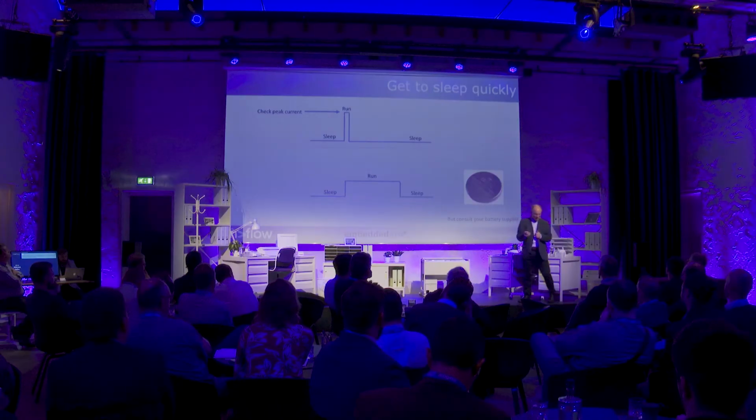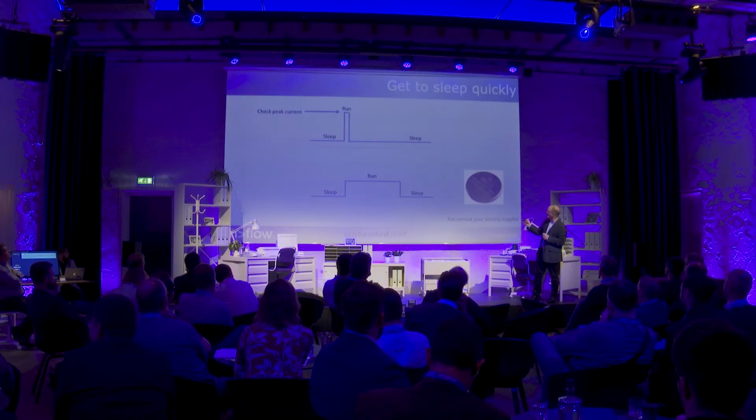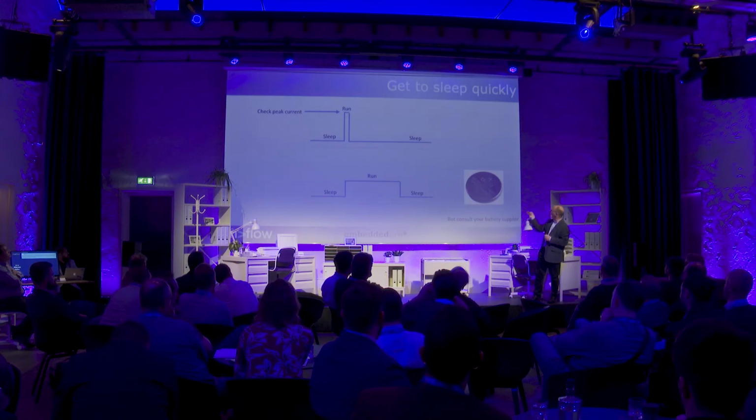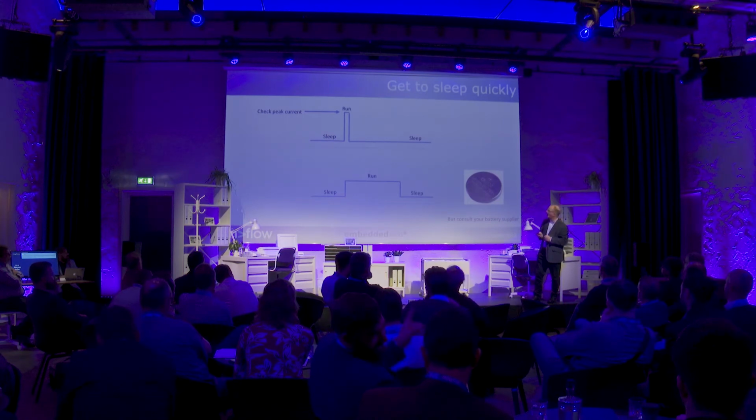Okay, just a word, and maybe Tom will talk about this in a moment. Of course, just check the peak current that the system is taking when you're running as fast as possible, because that current may be in excess of what the actual battery that you're using is able to take.